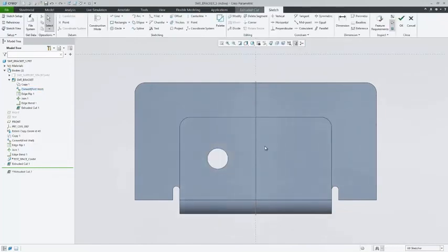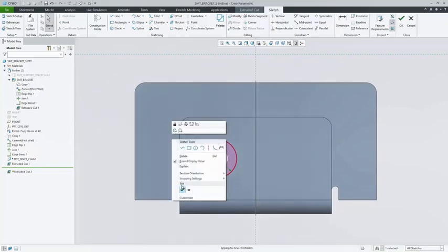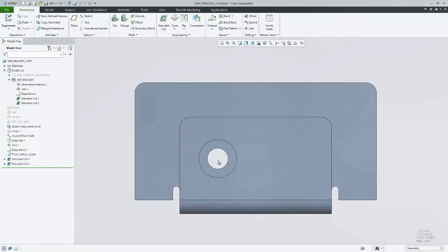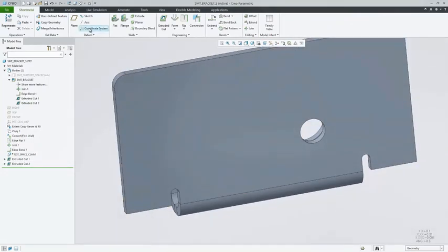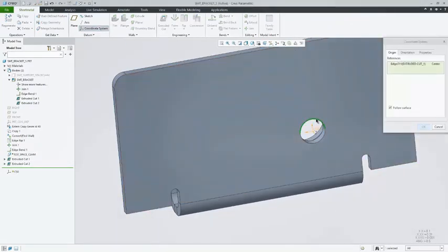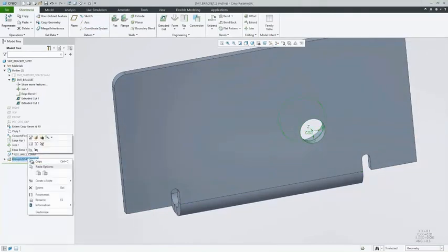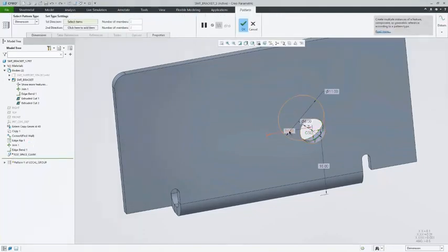A multi-body part in the sheet metal environment can contain a single body of the category sheet metal and optionally multiple bodies of the category basic solid. That means you can work with a sheet metal body in context of other regular geometric bodies. These can represent construction bodies as illustrated so far, or be regular bodies of type basic solid.